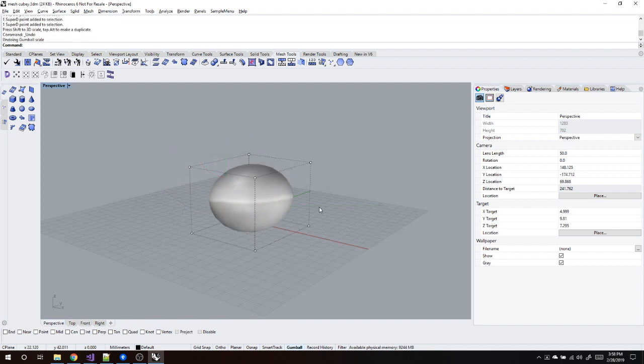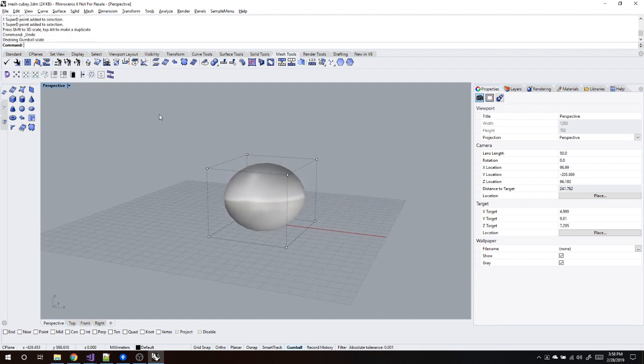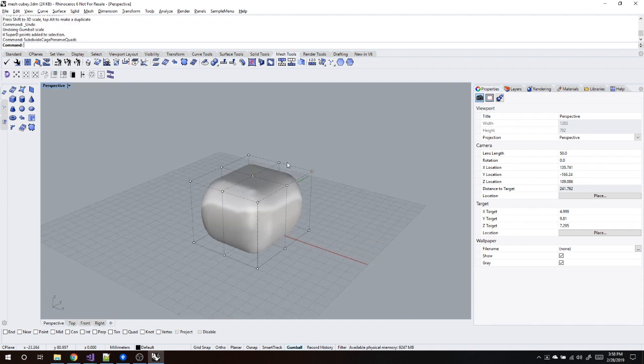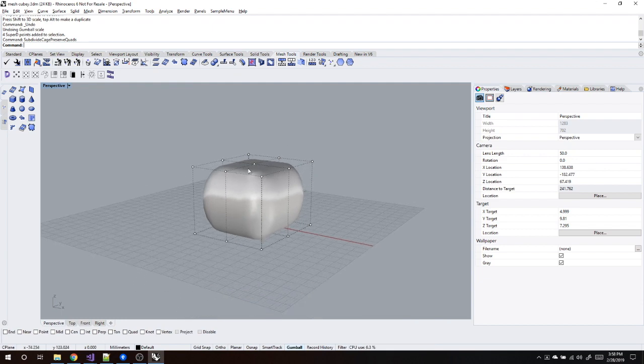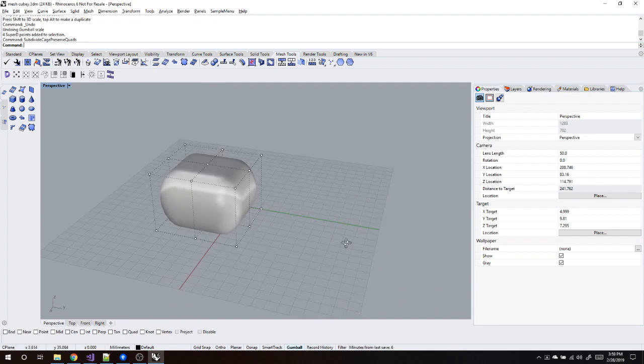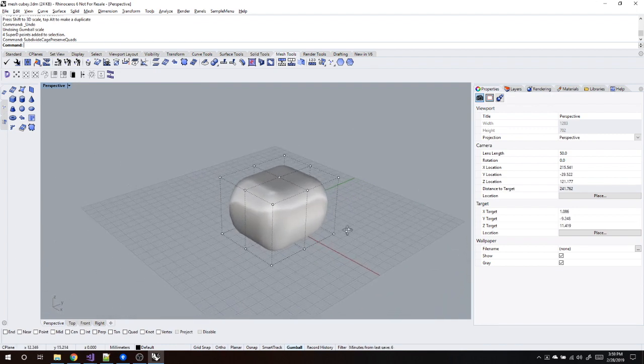If you want to do some basic editing, there's a number of tools on the SuperD toolbar that will allow you to achieve this. I find one of the most useful ones is actually the Subdivide tool, more specifically Subdivide Preserving Quads, which will split your selection based off of the edges subtending from the control points that you've selected and propagate all split edges around the surface while preserving quads to keep your object shape nice and clean.